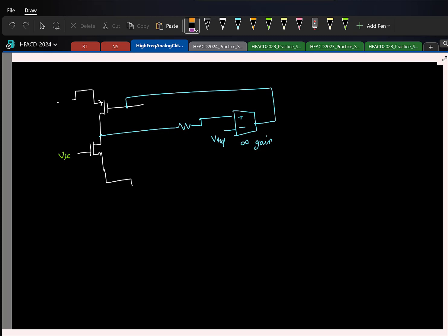So now what can you say about the small signal current here? 0, because we have open. So if the small signal current is 0, what can you say about the small signal change? Which means in this case, let us say the output was initially at some VREF, and at this instance you apply a common mode jump. What can you say about the output? It will stay the same, right? Now of course you might ask, we will not have an ideal current source, so what will happen? So let us say the current source has a small signal resistance Rx.